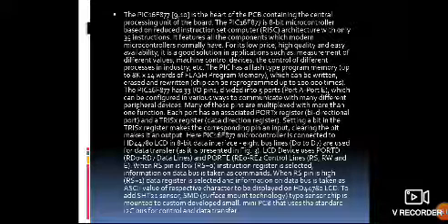The PIC has a flash type program memory which can be written, erased, or rewritten, and can be configured in various ways to communicate with many devices. Many of these pins are multiplexed with more than one function. Each port has an associated PORTX register.